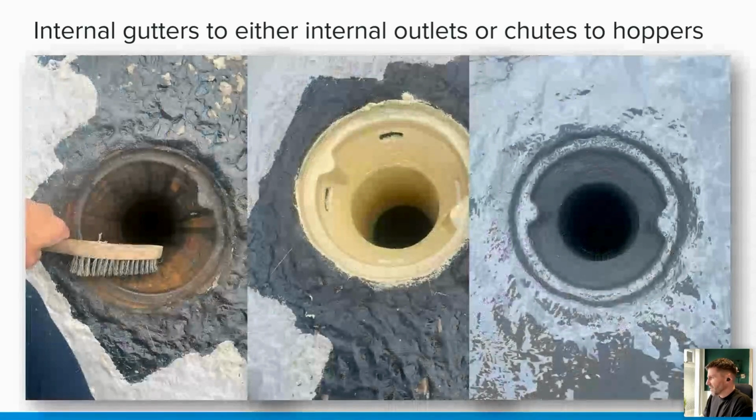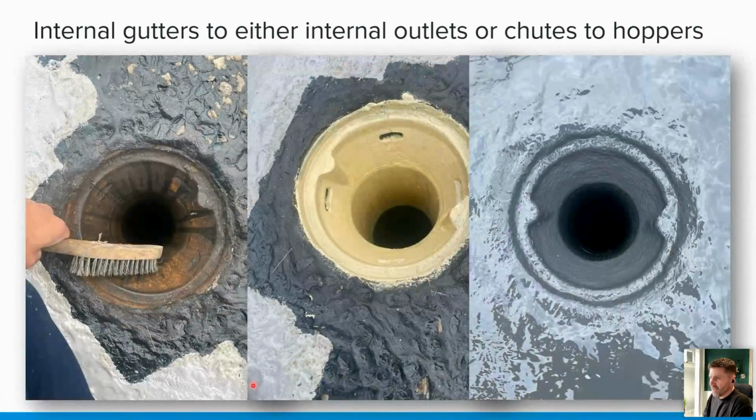So like I said, good practice with a liquid. This is a steel outlet here that they're preparing with a wire brush, taking all of that rust and corrosion off. This will be the primer that's going on, metal primer, and then the liquid waterproofing then taken down, finished on the downward facing edge. Really good practice there. Nice, neat job when it comes to a liquid system.